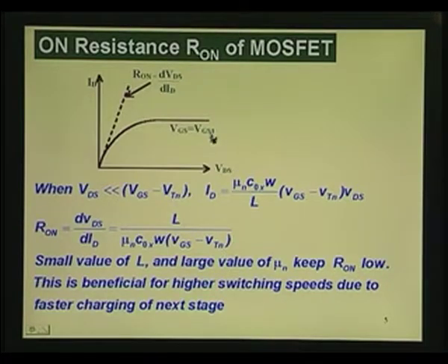So, here you can see this curve is linear in the initial portion, and that linear portion has a slope which is actually delta Vd by delta Id. Okay. That is the on resistance. So, this change in voltage divided by change in current, which is the inverse slope of this, is actually the on resistance. The resistance of the device when it is just in the on state. Okay. That is actually what we are saying here.